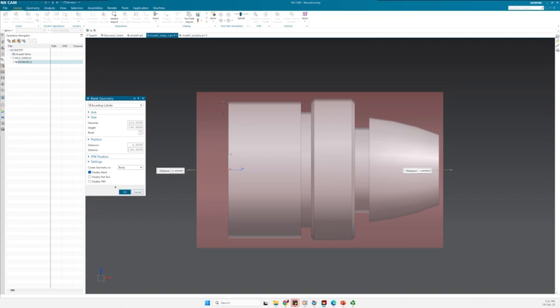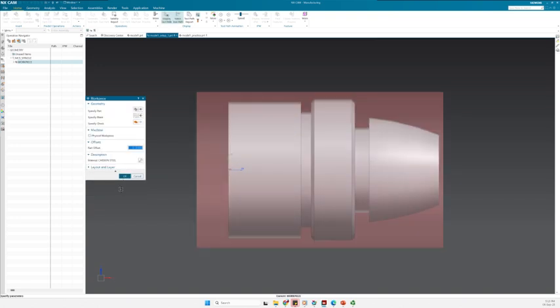automatically, and the cutting tool might also take maybe 2-3 millimeter. So anyway, I have something like 2 centimeter, or let's say around 20 millimeter for clamping with the spindle, which should be okay. So finally, the dimension of my raw stock is 110 millimeter in diameter and 170 millimeter for height. All right, click here. We have defined this one now.